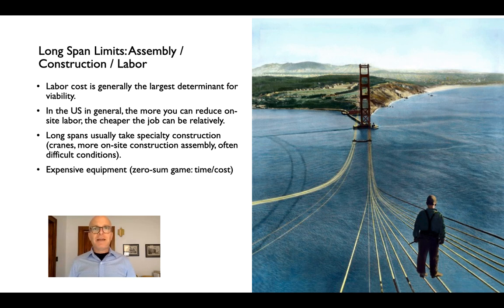In long spans, this is complicated by the fact that we need specialty construction equipment, very, very large cranes that have to move big pieces around. And what we may find is that there's a trade-off between the size of the thing that we can make in the factory and the size and time it takes to lift a big piece or to lift many, many small pieces into place on a job site. The trade-off we'll often find, right, is a zero-sum game between time and cost. If we break the thing down into very, very small elements, we'll need a smaller crane, but it may take much more time to put all those elements together. If, on the other hand, we prefabricate the long span in very, very big portions, it may take less time, but we're going to need more specialty equipment to get it into place.